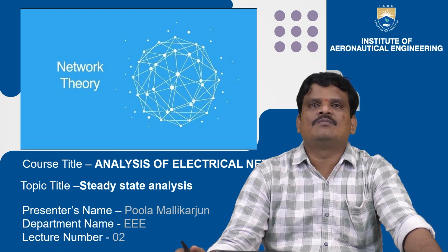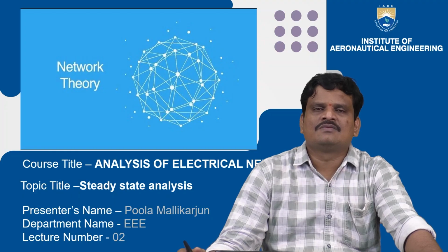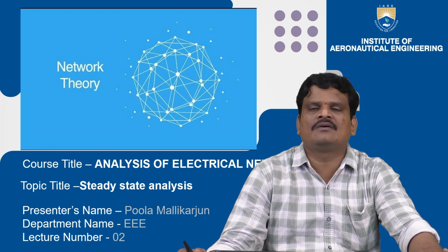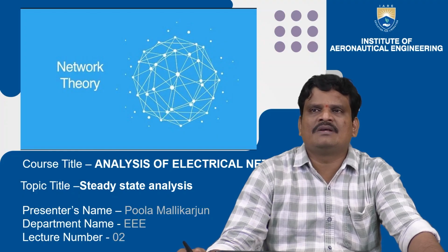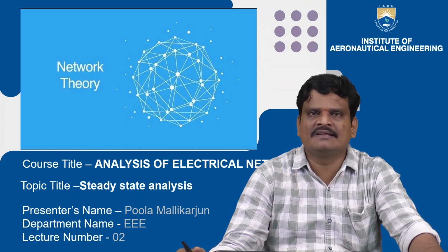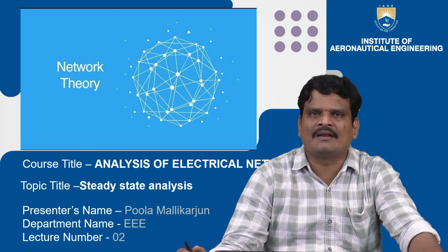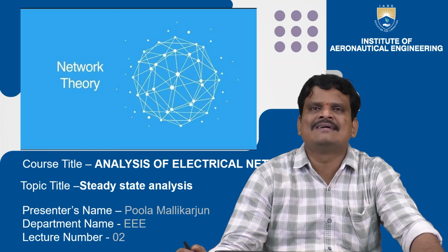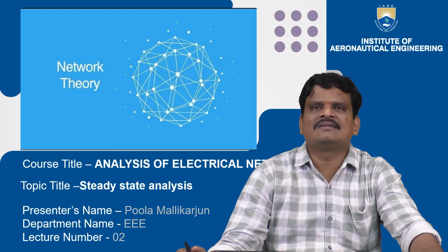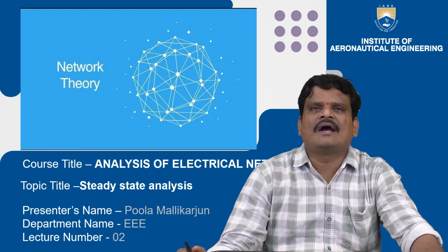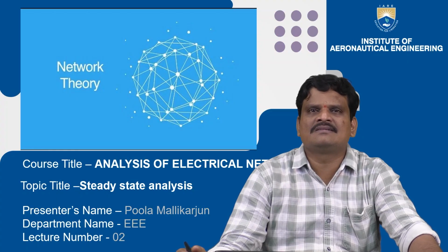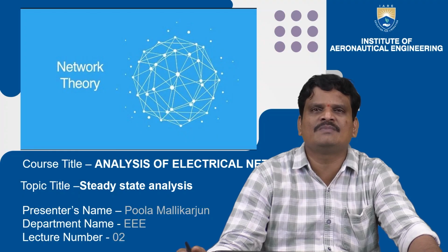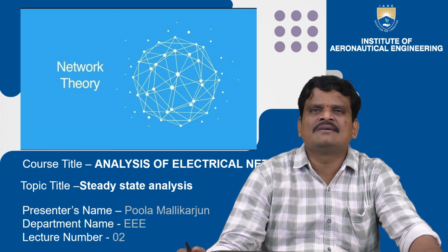Today we are going to discuss the steady state analysis. We are trying to calculate the steady state analysis output for different combinational circuits, where the elements are connected either in series or in parallel. In today's class, we are going to discuss the steady state analysis of a series RL circuit. That is, I am connecting a resistor and an inductor in series and analyzing the response, the steady state response or output obtained for a series RL circuit.